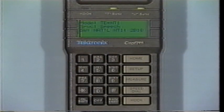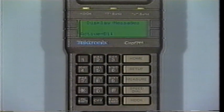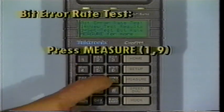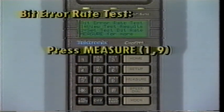To run a bit error rate test, or BERT, you must first establish a call to a loopback circuit, such as a 108 test line, or to a unit capable of sending a standard bit pattern, such as another Craftek. Then go to the BERT menu by pressing Measure 1, 9.